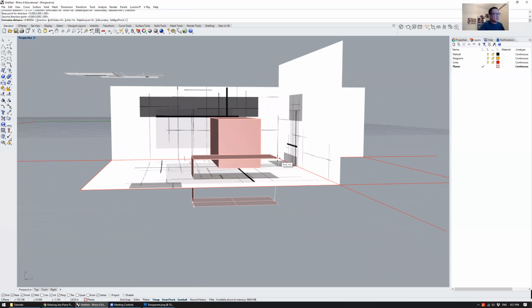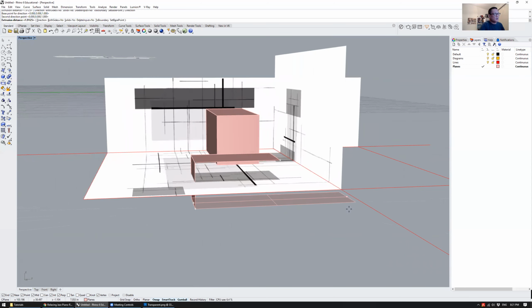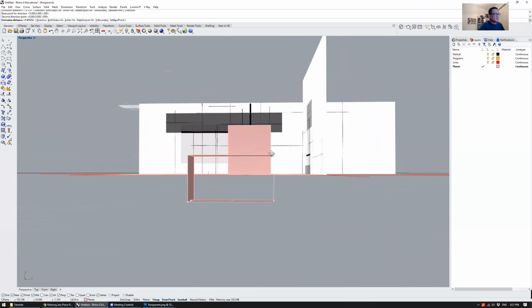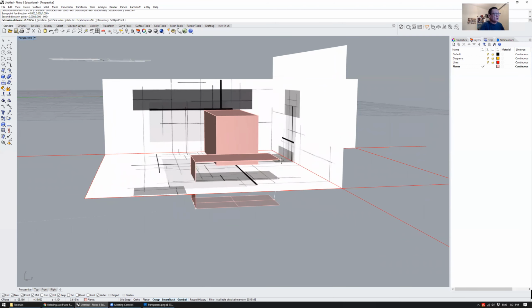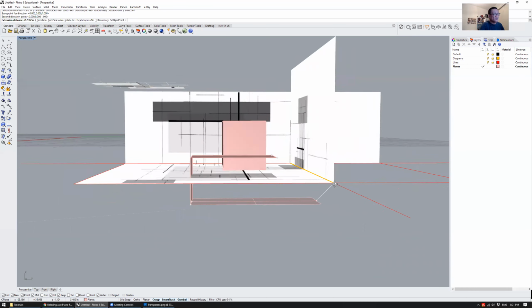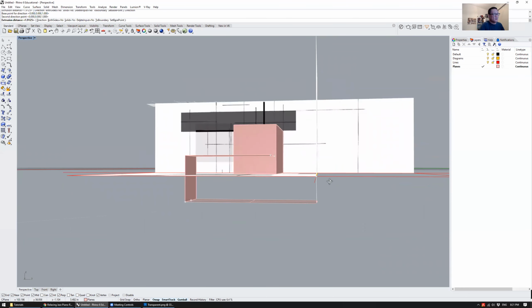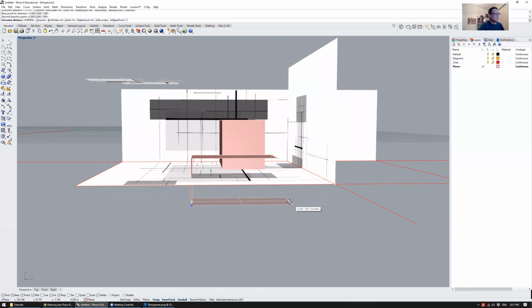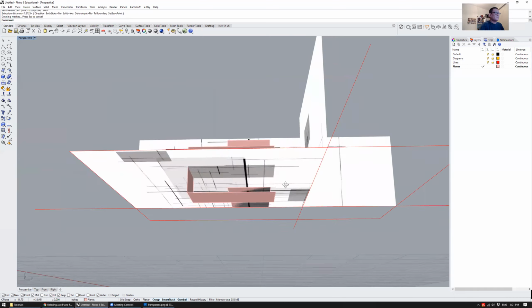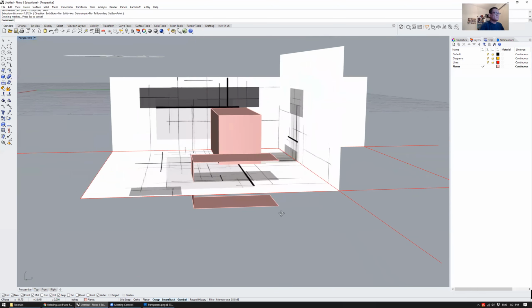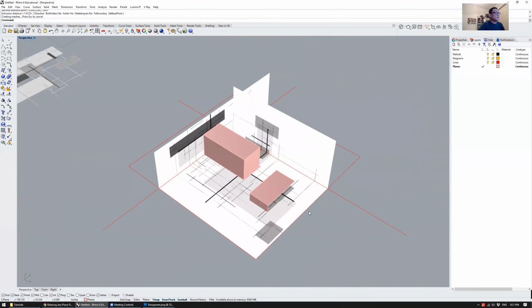And what's also nice is that when I'm going this way, because I've already constrained my extrusion to one direction, I can snap to things using my object snaps, and it will make it exactly the same length as what's above. Or I can snap it to this corner, and it will make it exactly the same length right to there. Or you can just arbitrarily end it anywhere you want. So this is kind of useful for that sort of stuff. Okay, cool. So that's the ExtrudeCrv command.